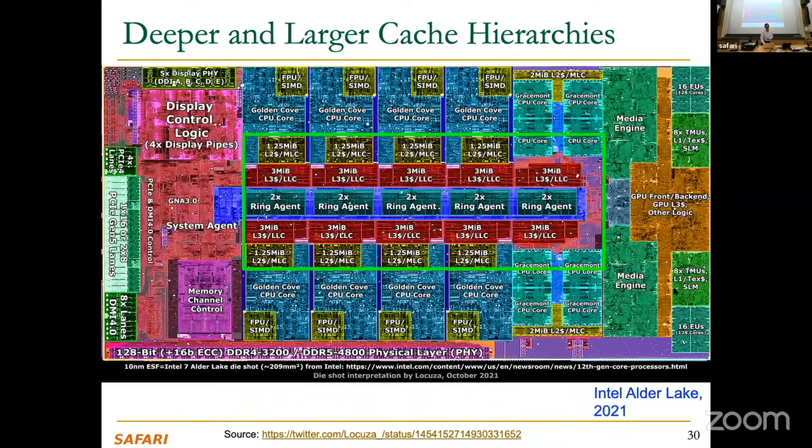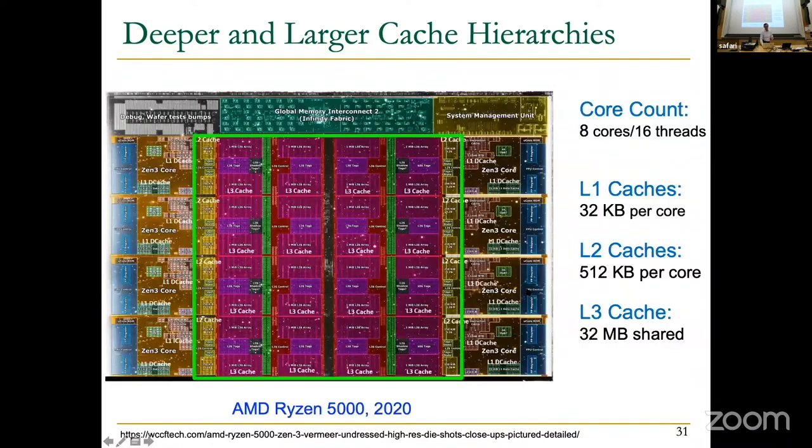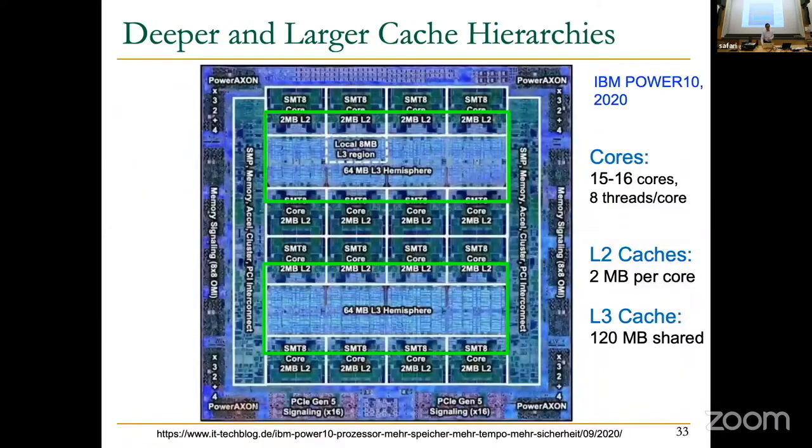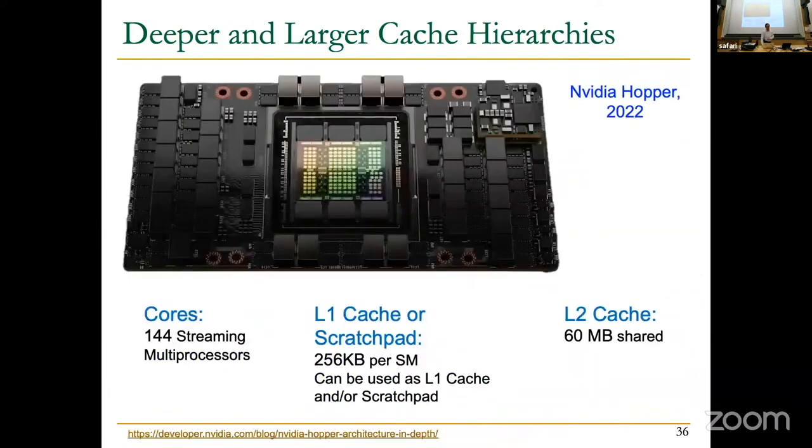Okay, so this is just to give you some examples that we've seen earlier. And it also shows how big these things that we're talking about are. So this is the reason why L3 caches are not accessed in parallel in terms of tag store and data store. You access the tag store first and data store next, because this is a huge cache, as you can see, right? You don't activate a huge amount of your chip just to get data that you're going to miss on anyway, that you're not going to need anyway. Okay, and this is true everywhere.